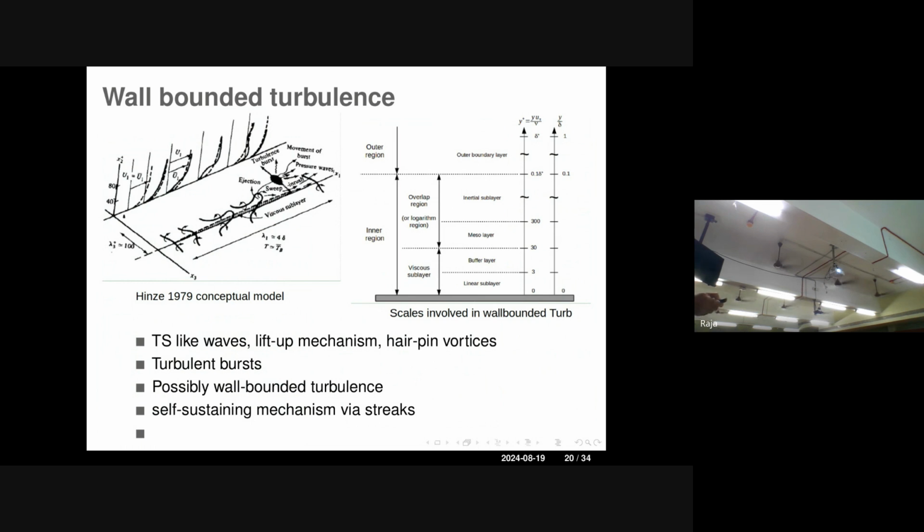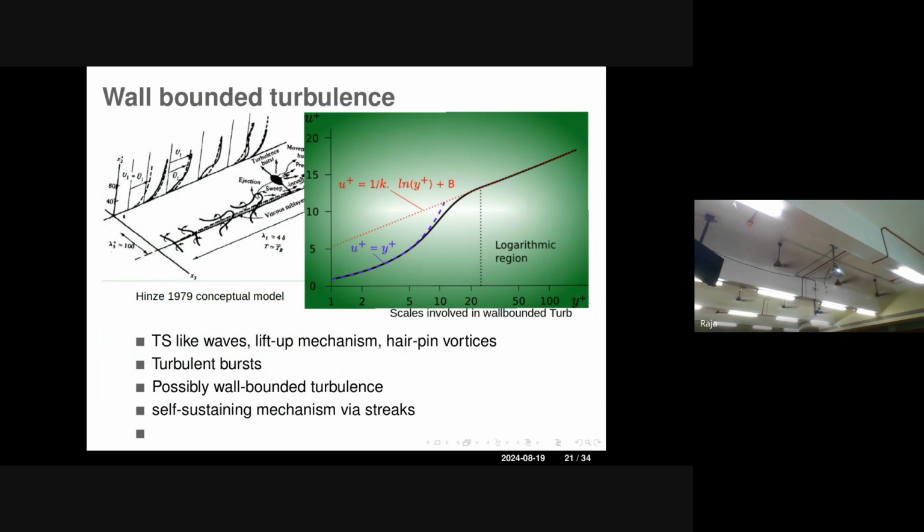These are the zones where some parts move very fast and the rest move very slow compared to the mean flow. So you always have shear, rotating and elongating structures, and high-speed and low-speed streaks that one will be seeing. And these particles get suspended and modified, and break these structures. And what people have known for the past 100 years is that there are always common logarithmic regions, in terms of how the velocity profile varies with the wall-normal coordinate.